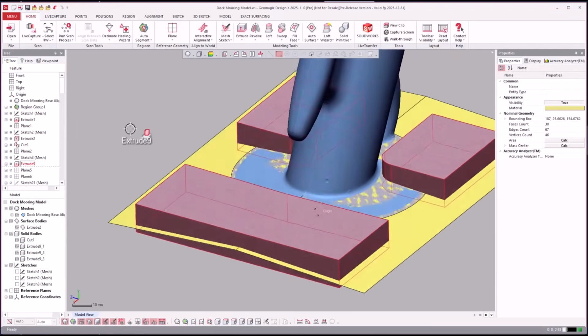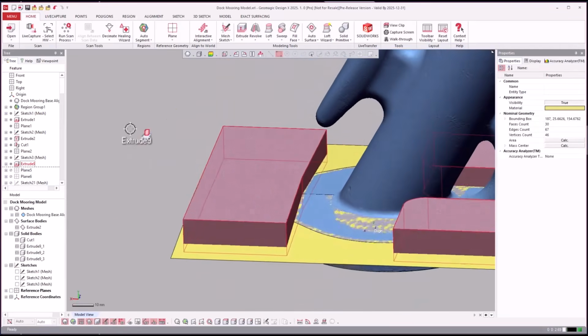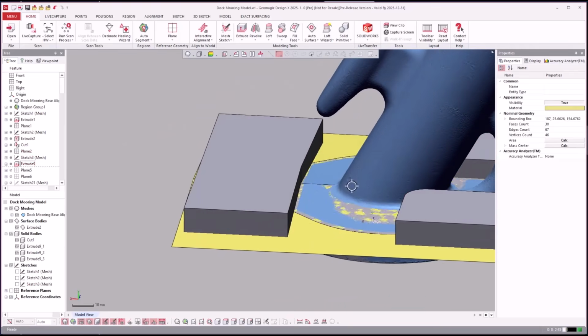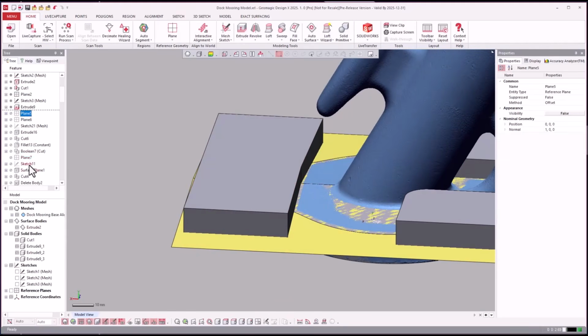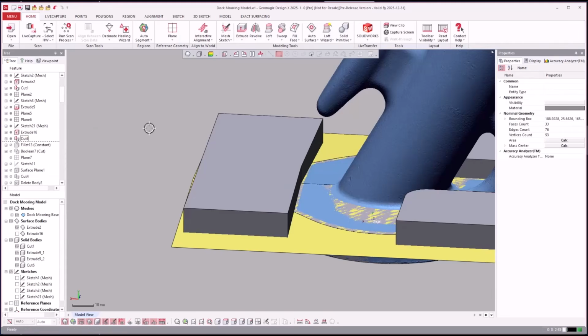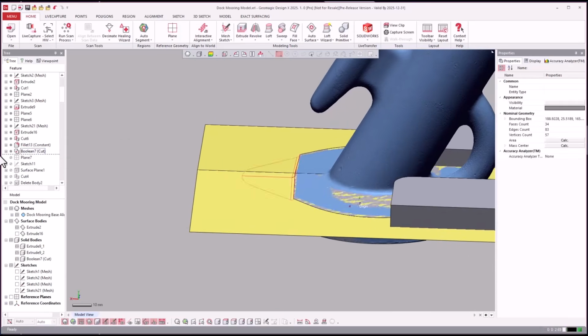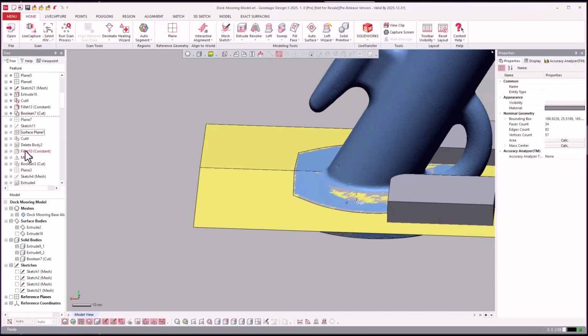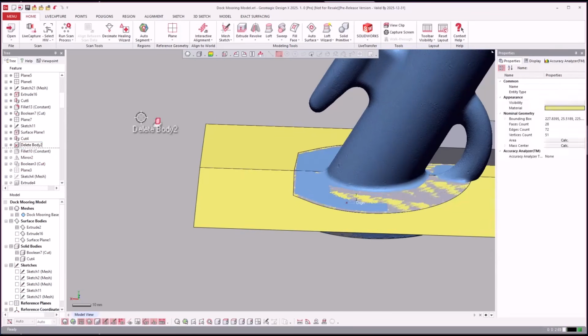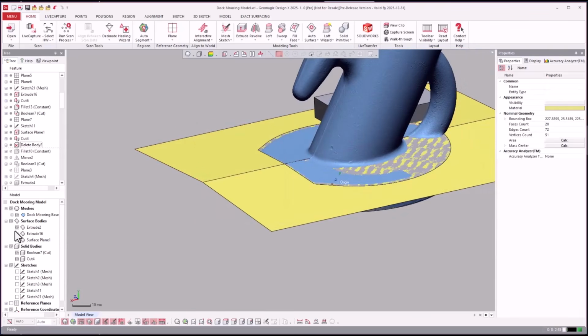And then the little base plates where you mount it that are actually level, because this has draft on it. And then Boolean cut those away. And we'll turn the surface off.